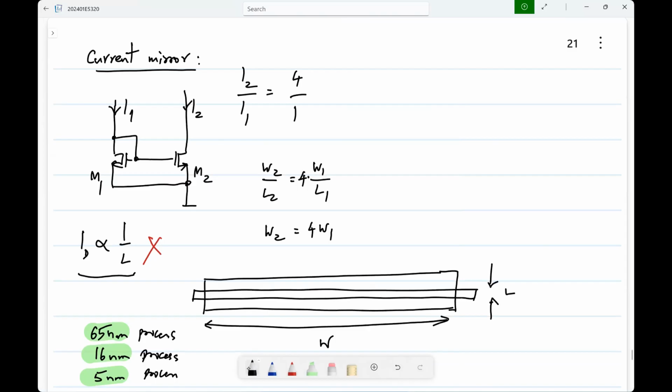So basically, you know that if you have parallel connections of MOS transistors, it's like adding up their widths, right? And anyway, we also know that we need to make unit element based design. Okay.